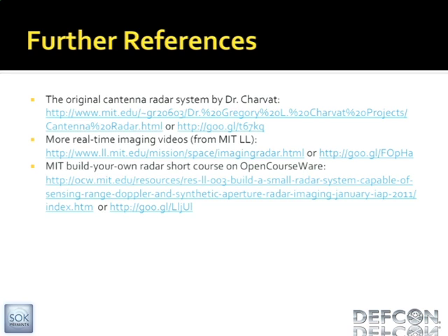But basically, it's going to be hard to see inside this thing, so you might just have to come back later and see. But the way this works is there's an SMA connector in here, and there's a little wire being fed into here. So this is basically a waveguide port. It's an adapter from that little feed antenna to this larger waveguide. And then it's basically a crappy directional antenna. But you could use something like this for Wi-Fi too, if you wanted to make your signal more directional. It's the exact same principle. And if you took some of those really big Wi-Fi antennas, you could make a highly directional system just with that.